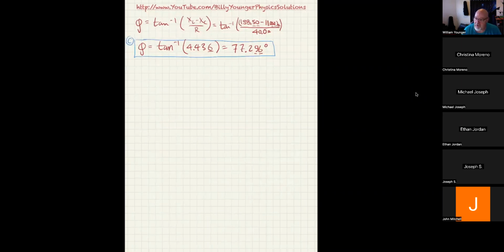So if you actually looked at the voltage through an oscilloscope, you would see the voltage through the capacitor, and that would just look fine. But the actual voltage coming from the power supply versus the actual voltage going through the circuit, you'd see that it's actually ahead by almost 90 degrees. In fact, 77.3 degrees roughly. So that's really what that's showing.